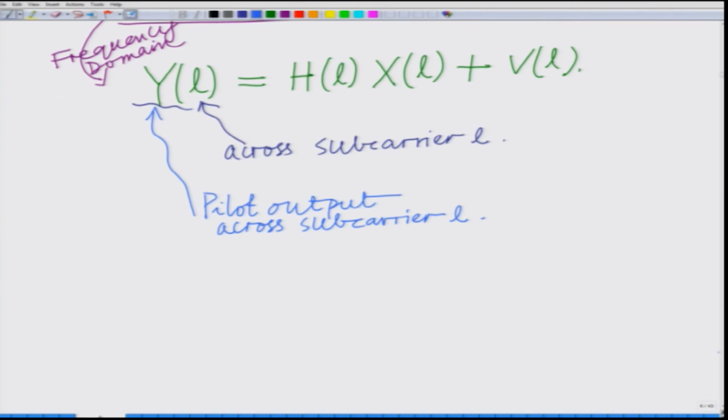So, what we have done so far is we have considered a simple n equal to 4 subcarrier OFDM system. We have loaded the symbols capital X0, capital X1, capital X2, capital X3 onto the subcarriers, performed the IFFT or the IDFT to generate the time domain samples, added the cyclic prefix, and looked at what happens at the receiver once you take the FFT.